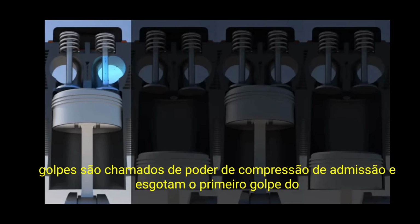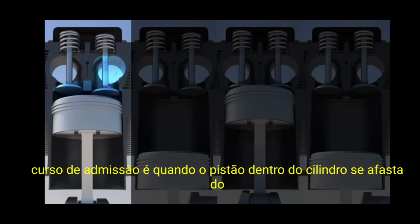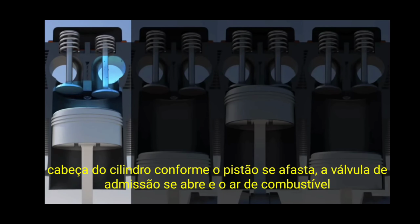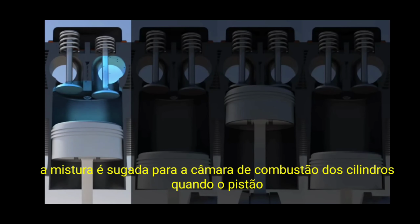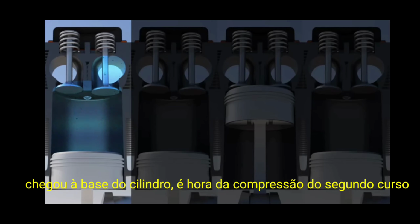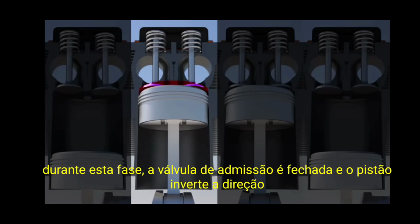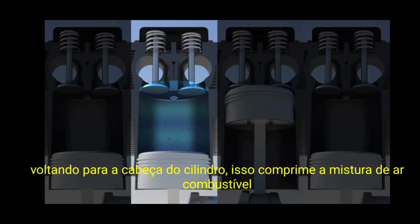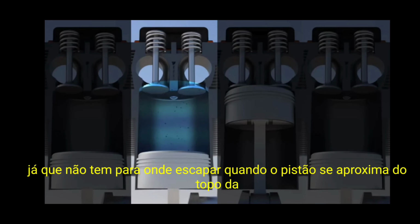The first stroke, the intake stroke, is when the piston inside the cylinder moves away from the cylinder head. As the piston moves away, the intake valve opens, and the fuel-air mixture is sucked into the cylinder's combustion chamber. Once the piston has reached the base of the cylinder, it's time for the second stroke, compression. During this phase, the intake valve is closed, and the piston reverses direction, moving back towards the cylinder head. This compresses the fuel-air mixture since it has nowhere to escape.